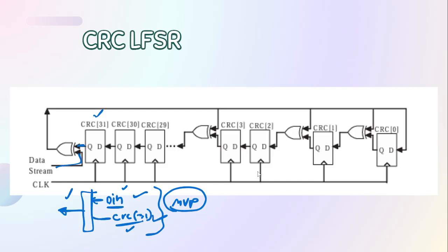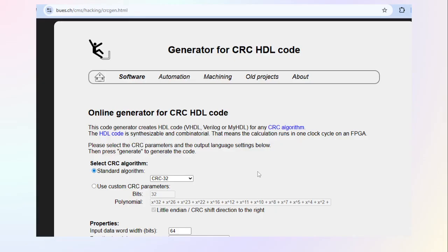And all the theory will be based on the fact that we are rolling this LFSR function to many bits, 256 bits in my case, but you could make it however many bits you want. Okay. Now I'm going to describe how people who use functions to do CRCs, how that works.